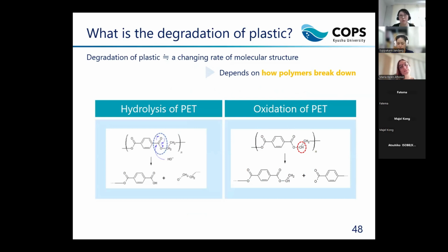All right. The basic is, the carbonyl index is an indicator to check the level of oxidation, meaning the degradation of the plastic. After getting UV light, the plastic releases CO2 and takes oxygen from the surroundings, and the molecular components can change.